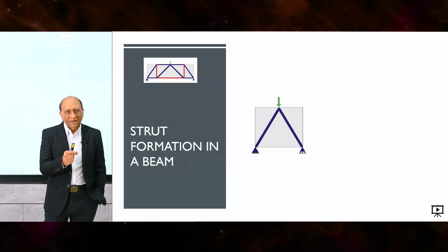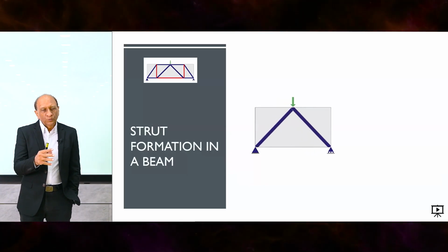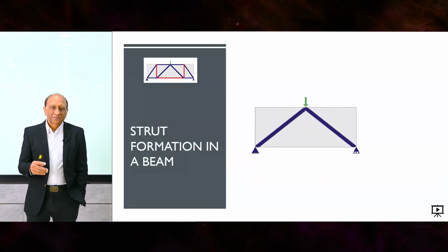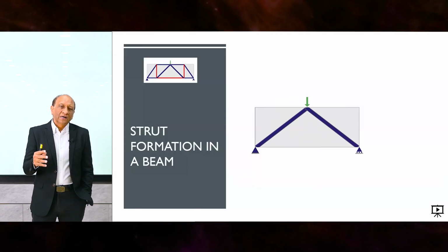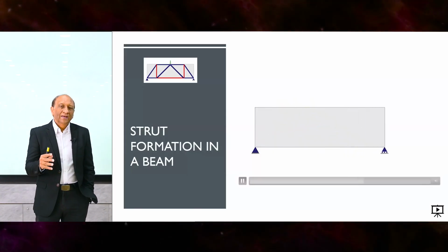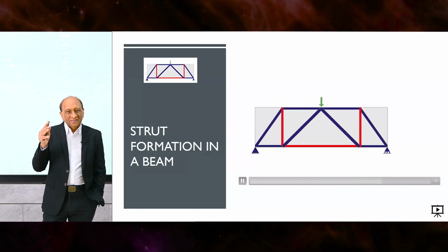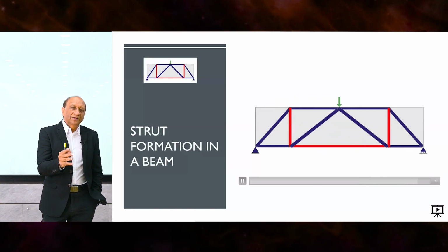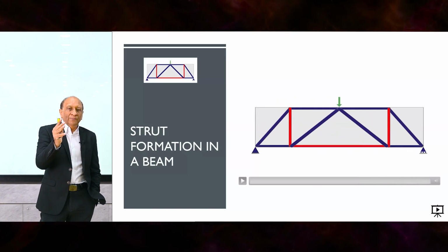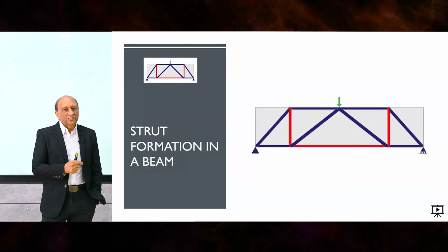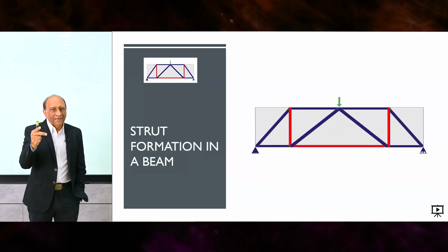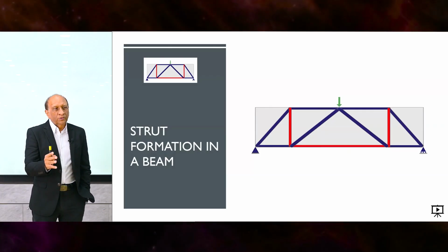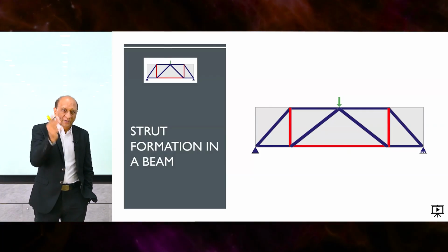It just shows that when you have a beam, and when you change the span, the struts will follow the span. And then it keeps on going until a time comes where the strut angle becomes too shallow, and then you may have to create a secondary load transfer mechanism. That means that the first diagonal will not reach the support, so you need to carry this load back up, and a second strut will bring it down. That's the principle. If you draw this thrust line roughly at 45 degrees, between 35 to 60 degrees, and if it doesn't hit the support, you need to carry it back up to the top and bring it back again.